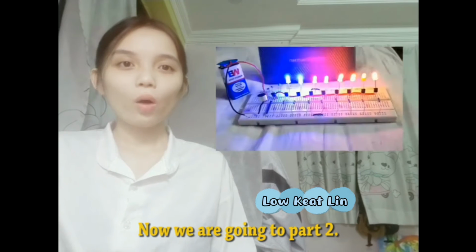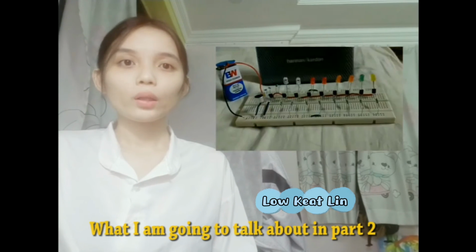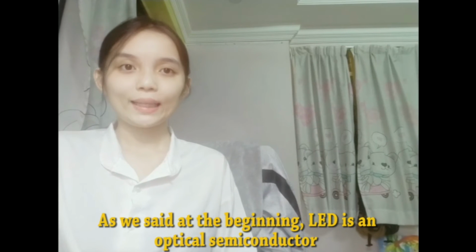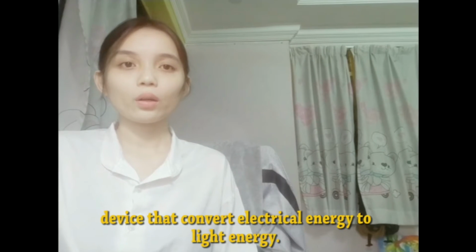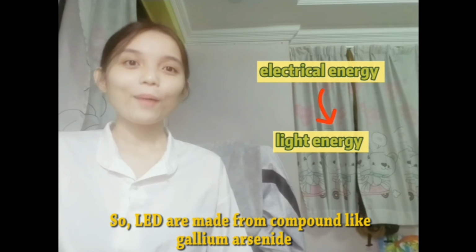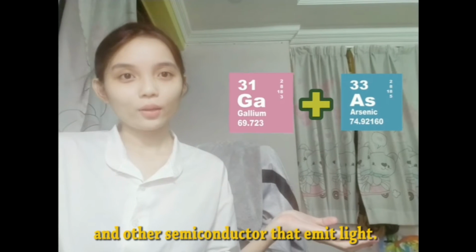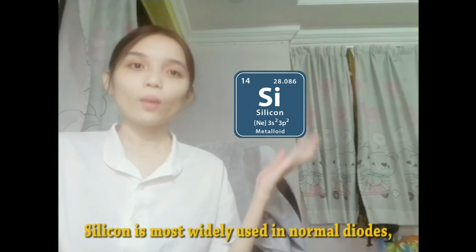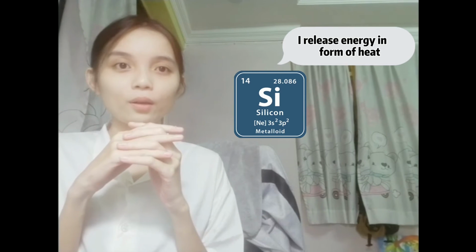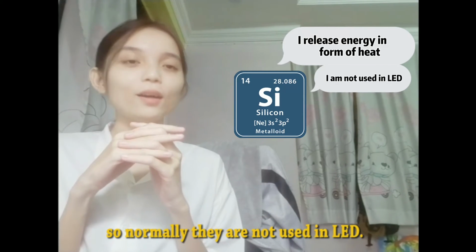Now, we are going to part 2. What I'm going to talk about in part 2 is the basic operation of an LED. As we said at the beginning, an LED is an optical semiconductor device that converts electrical energy to light energy. So, LEDs are made from compound semiconductors like gallium arsenide that emit light. Silicon is most widely used in normal diodes. However, it does not release energy in the form of light. So, normally it is not used in LEDs.